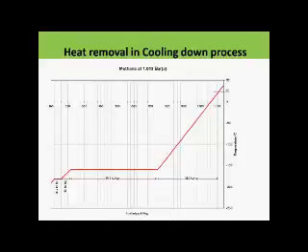So this is what is happening in the heat removal in the cooling down process. We are bringing the temperature down. We are removing heat, for example, 380 kilojoules per kilogram. We have taken it from plus 25 to minus 161 degrees, and then we further go down.